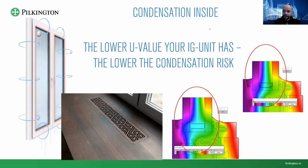As you can see, the cold zone, so from blue to green, is much bigger and much wider on an aluminum one. And the edge zone is looking much warmer and better with the warm edge. So if you are trying to promote your IG units and windows in the colder climates, it is usually advisable to use a warm edge in this case.